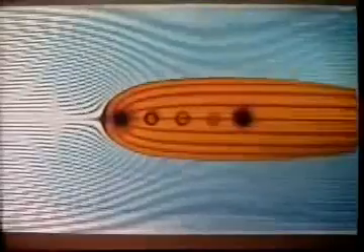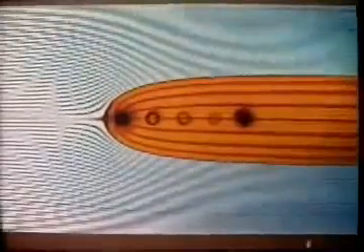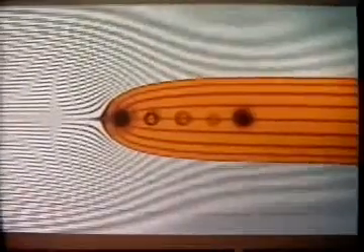When the rate of fluid flowing from the source is constant, the streamlines are sharp. But when the flow from the source changes, the lines of colour become blurred because the faster particles, midway between the top and bottom plate, no longer find themselves close to the lines of slower particles which started earlier from the same neighbourhood.